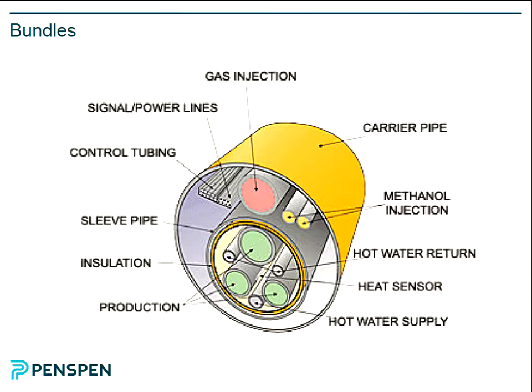How do you install valves and some fittings on this kind of bundle? That's a very good question, and yes, you can. They've installed these bundles with massive manifolds on them. They've installed them with subsea isolation valves halfway down. They've installed them with massive manifolds on both ends. Certainly, it's quite usual to have a skid with all the flange connections on the end. It's like a submarine basically, so you can put a lot of equipment on it.